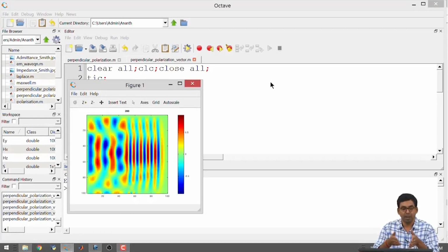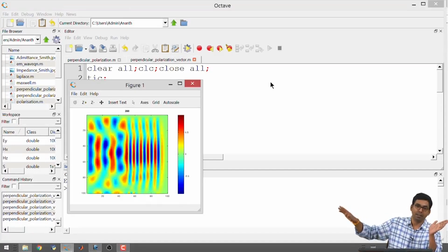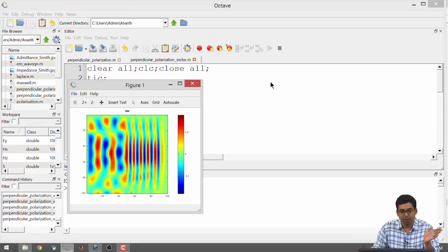In order to create plane waves going at an angle, all you need to do is define a source at different xy coordinates equal to some sine something. So how normally people do it is they will create a set of xy coordinates. They will just say that, okay, I want a line at 45 degrees to act as a source. So you'll just say y equal to mx plus c. M is going to be equal to 1 for 45 degrees. Constant is just depending on where you want to place the source, along the vertical direction.